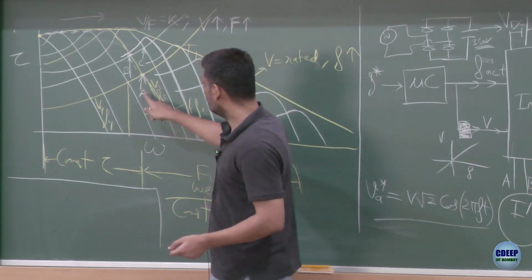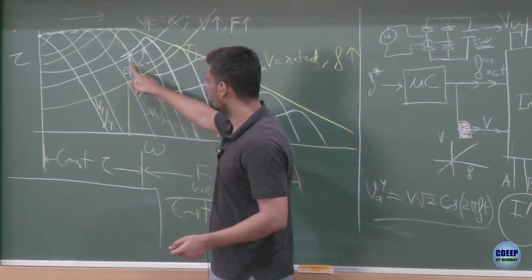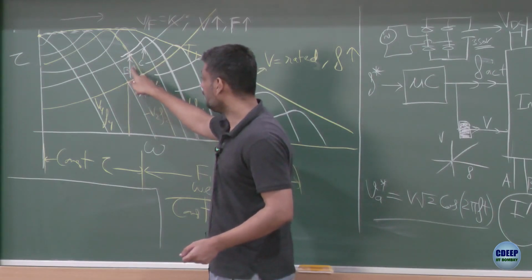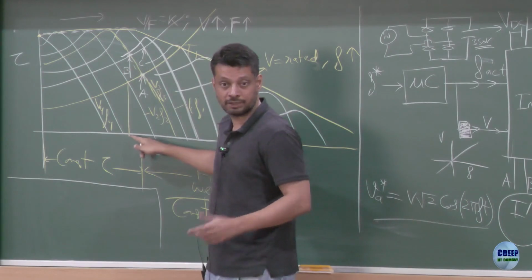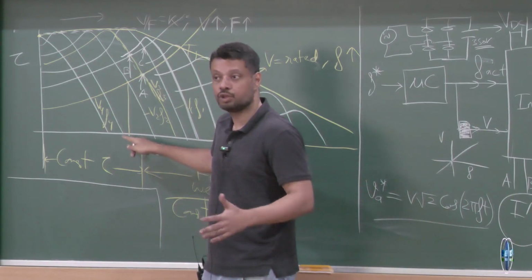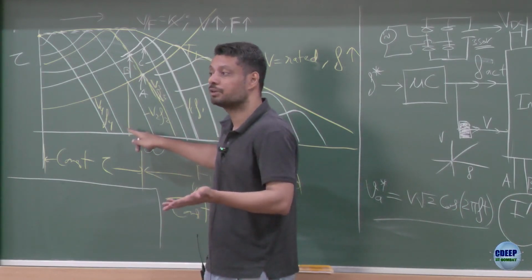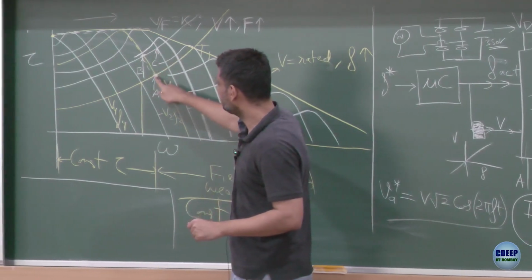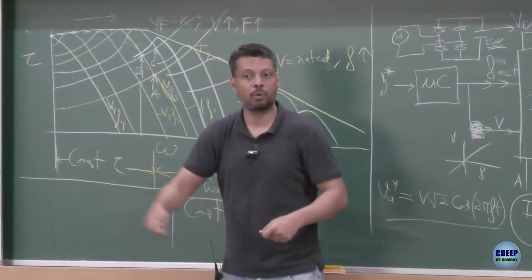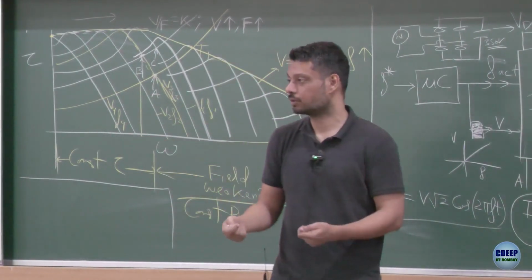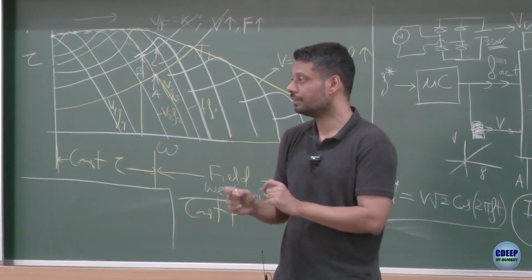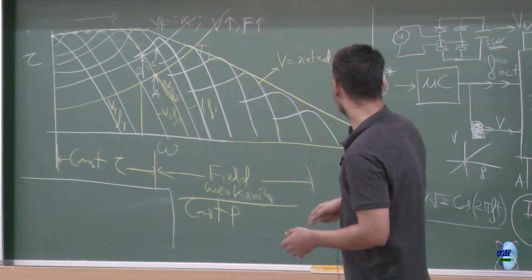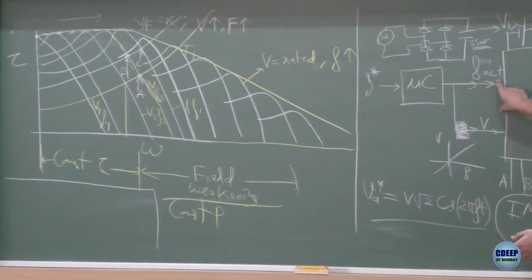What you can do is, if you are operating at A, load increases, you went to B because same frequency. Now at point B, you know the speed has reduced even though the frequency was the same. So you can ask your microcontroller to increase the frequency a little bit so that you move to C so that you maintain the same speed. So if you want to really do a tight speed control, a very regulated speed, you have to have some mechanism of measuring the speed, and then you can adjust these references coming out of these blocks.